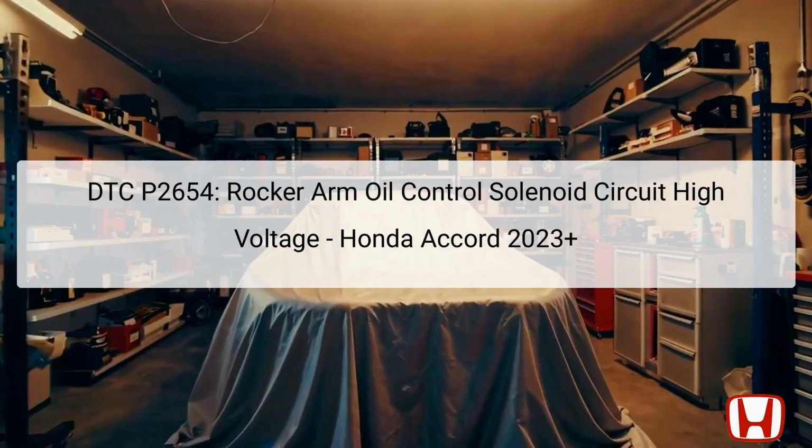The Diagnostic Trouble Code, DTC P2654, indicates a high-voltage condition in the rocker arm oil control solenoid circuit. Specifically, this code suggests that the engine control module, ECM, also known as the powertrain control module, PCM, received a return signal from the rocker arm oil control solenoid that is not within expected parameters. In essence, the solenoid is designed to manage the flow of oil to the rocker arms, playing a crucial role in controlling the variable valve timing (VVT) system.